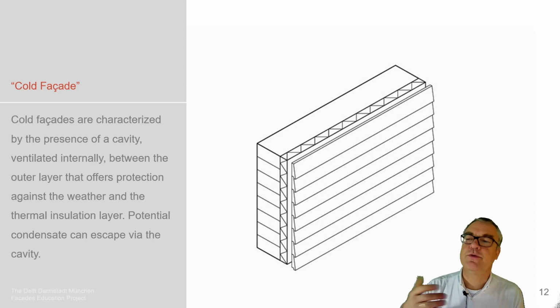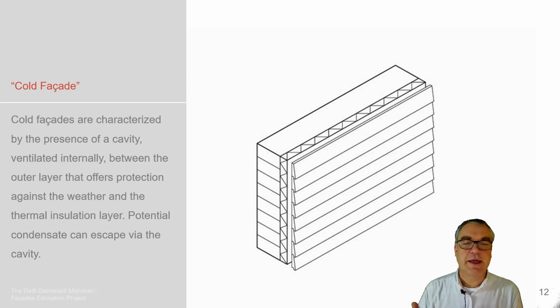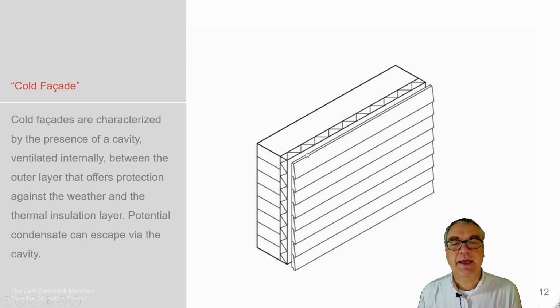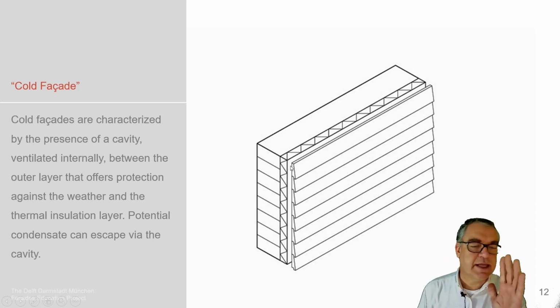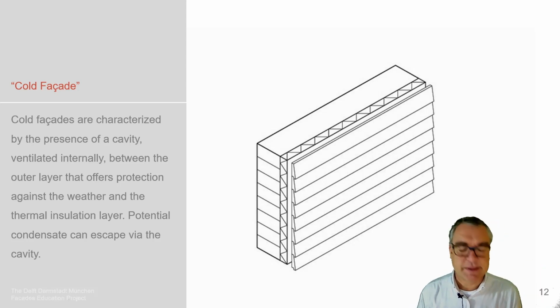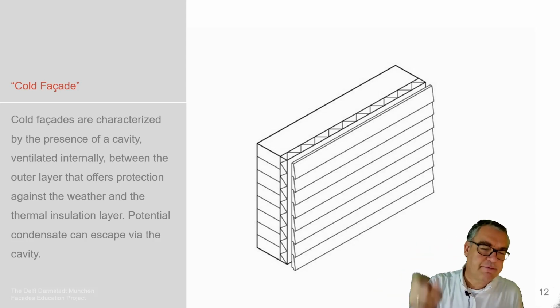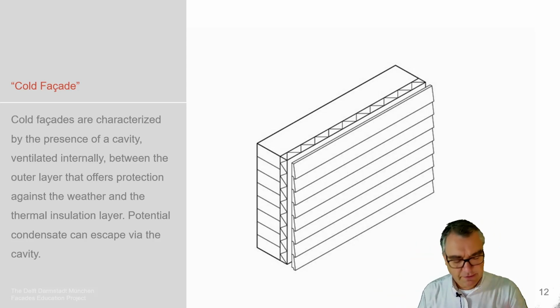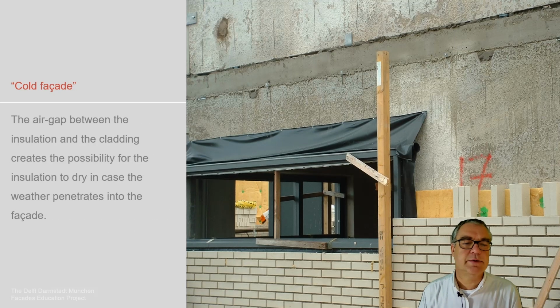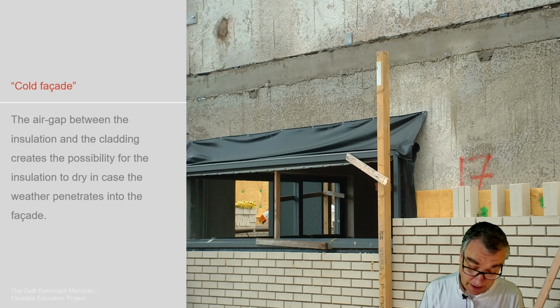In comparison to the so-called cold facade, cold in that way that we have this cavity here, which allows air to ventilate, and by that the insulation is positioned against the air, by that being positioned against the cold outside, and that's why we define it as a cold facade. We see an inner masonry structure, we see the insulation, we see the cavity for ventilation of the air, we see an outer cladding. Cladding could be done in various ways as we may like for our designs.